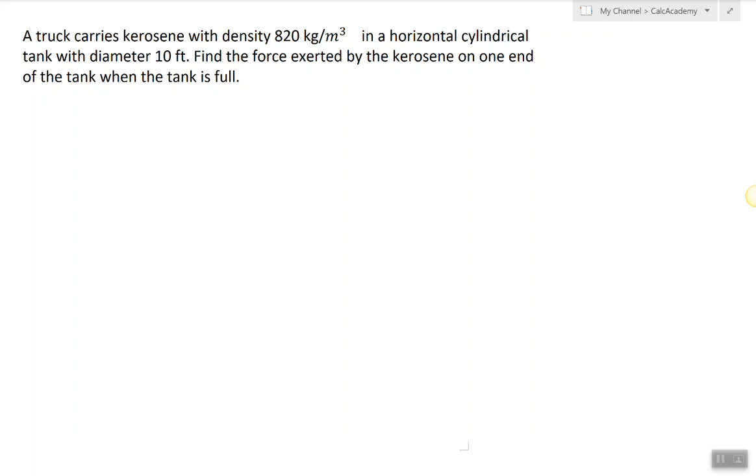In this video, I will show how to find the hydrostatic force exerted by a liquid on the wall of a container or anything submerged in the water. The formula that we're going to use is the integral from a to b of rho g h of x times w of x dx, where